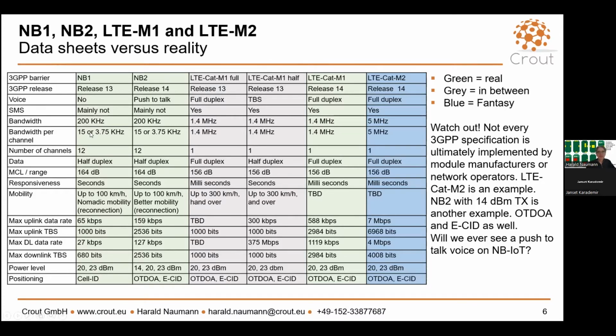A little bit about bandwidth. The bandwidth for 12 channels inside of an LTE band is for narrowband IoT 200 kilohertz only. If we go to Cat-M1, we already need 1.4 megahertz. And if we ever get M2, then we need already 5 megahertz. And M2 is faster, and M2 gives us already slow video options, but okay, it is then already in competition with LTE Cat 1.